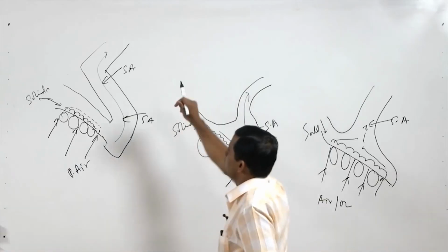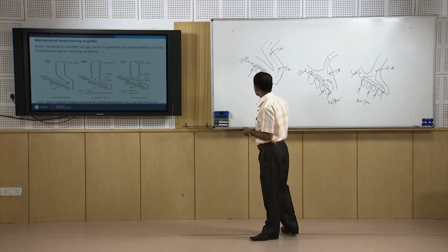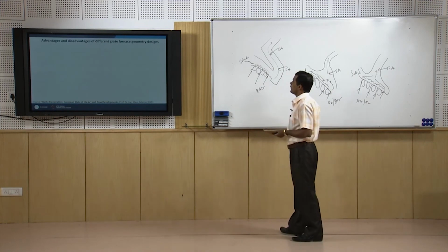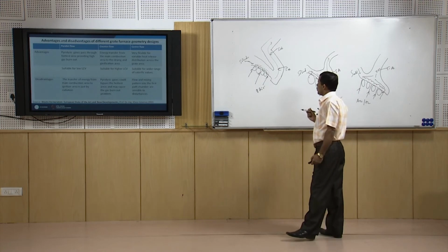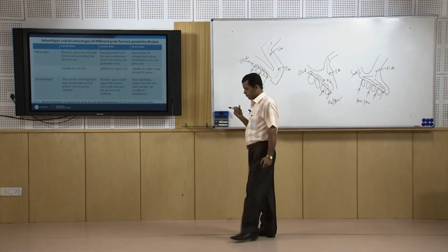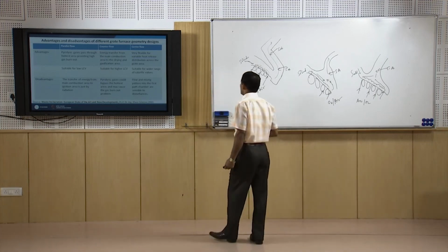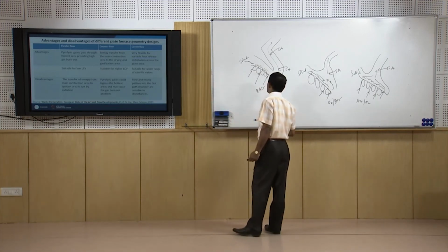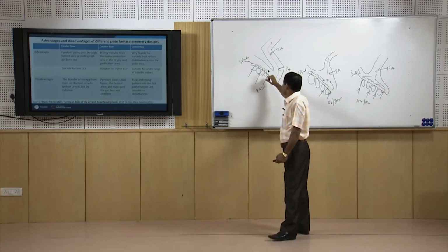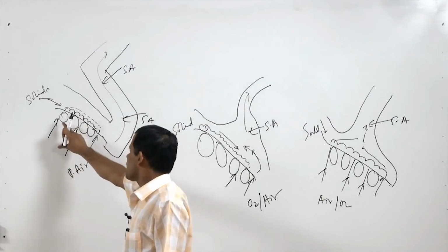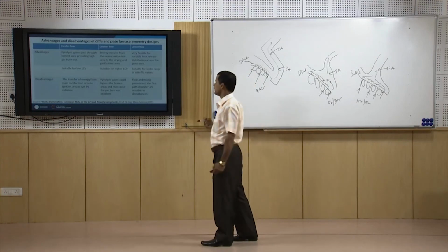When will we prefer which one? Say the material is having low calorific value, that means carbon content is less. So, that will be requiring more heating. So, obviously, the parallel flow mode will help for the handling of those type of materials.